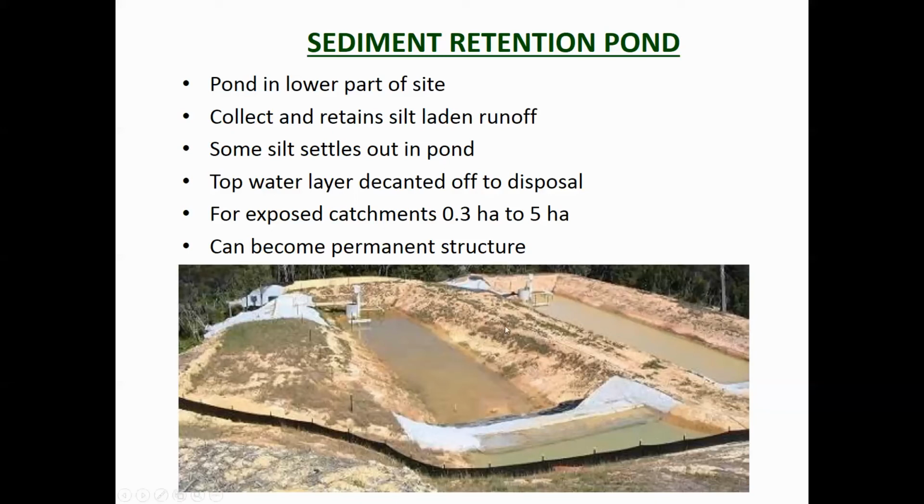So it's taking that clean water off the top, then it flows into this manhole there, then from the manhole it flows into the natural water system. Notice the manhole's got an open lid there, so if the T-bars get beaten, that there's too much flow going in, rather than sort of flowing over the bank there, it will go into the manhole. It will short circuit the system, but that's better than having the flow going across there. Now if that gets beaten, it's going to flow over this geotextile here into the natural water course.